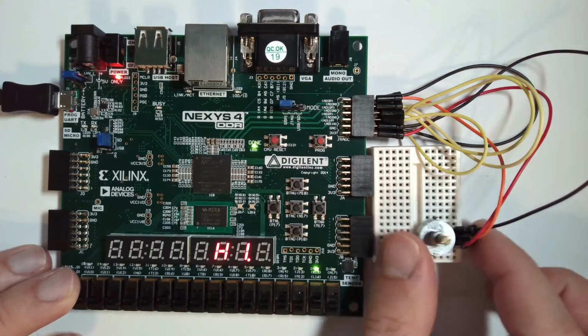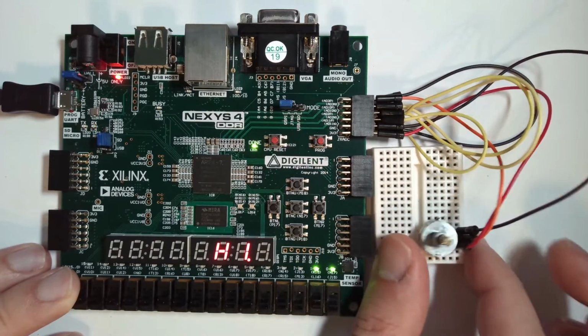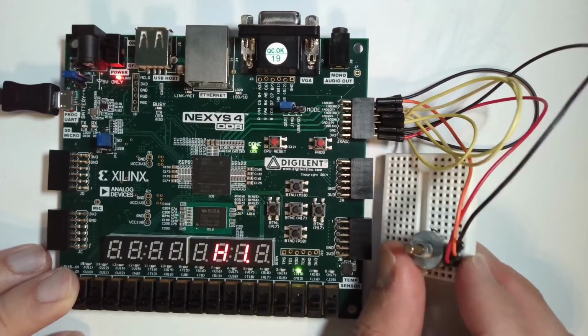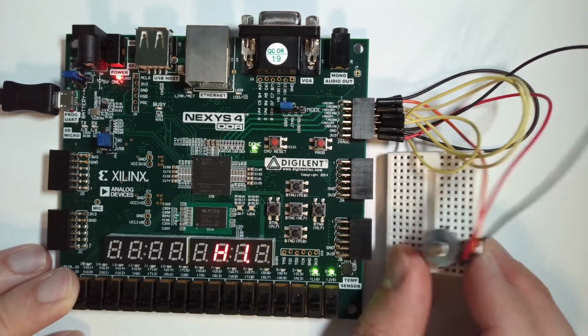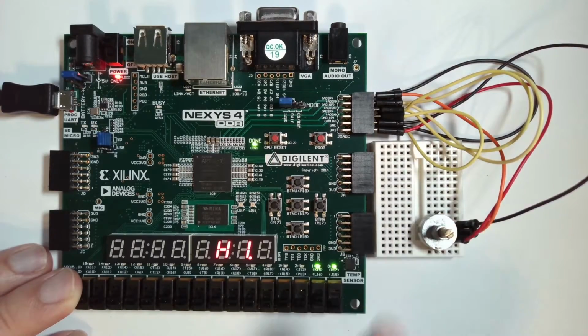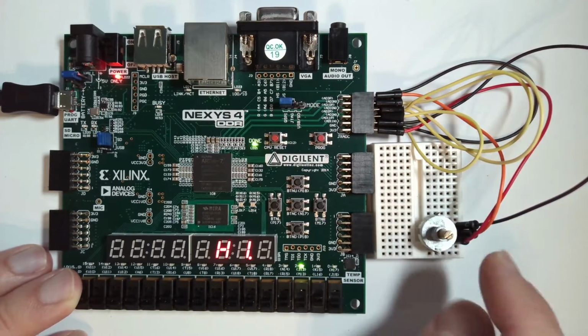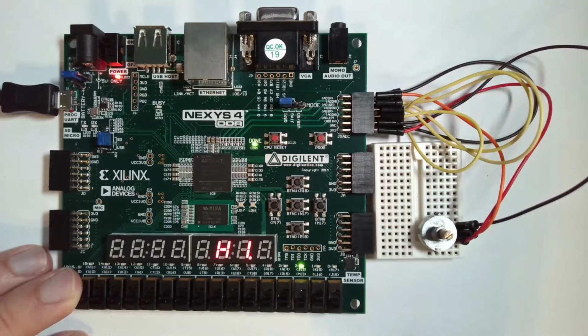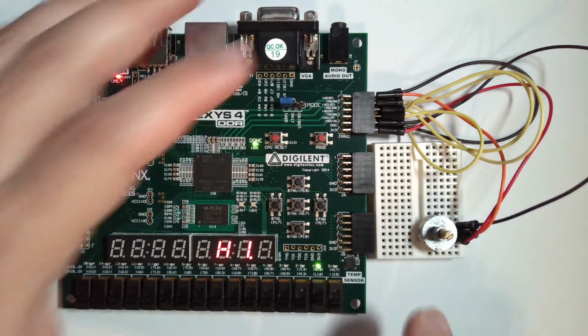What's happening is this is my voltage divider, and I decided to use a potentiometer for it. I'm not exactly following the specs I just showed you, and the reason is I don't have all the resistors, but this is as close as I can get it. It's close enough. It doesn't give me exactly 1 volt at the output, but it's close enough, as you'll see shortly.